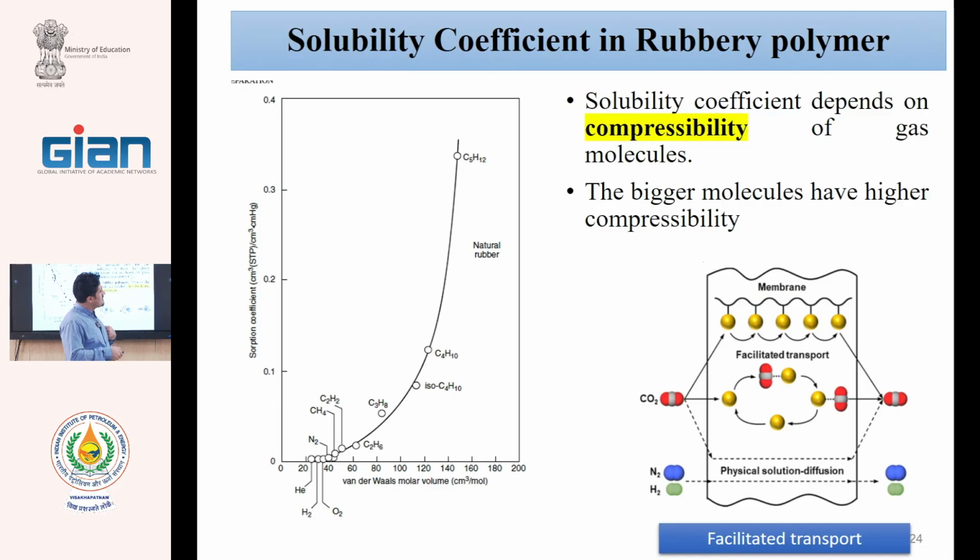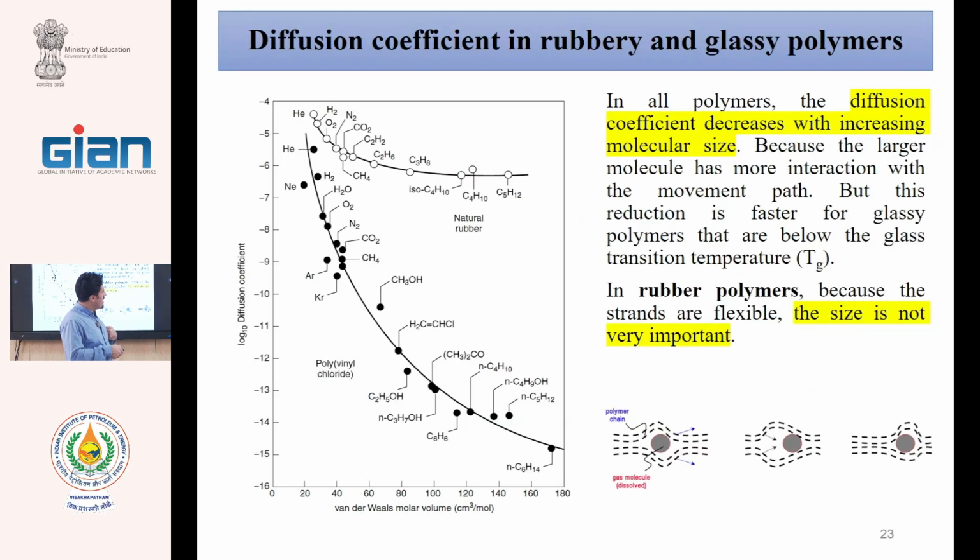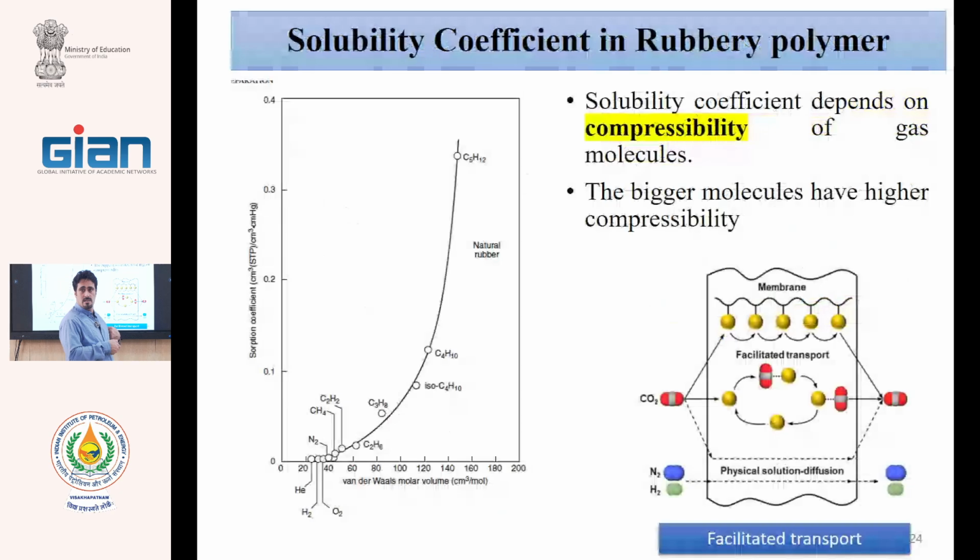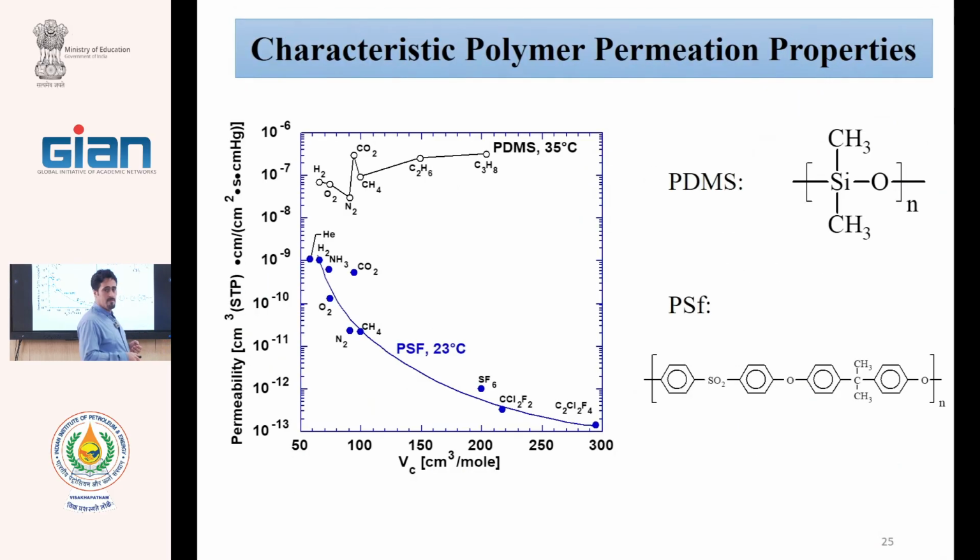In this case, where is the pentane? Here. Pentane has a very low diffusivity, but in this case has a high sorption. Therefore, we cannot use these two diagrams separately. We can merge them, and after the merge, solubility and diffusivity, we say solubility and diffusivity give permeability.